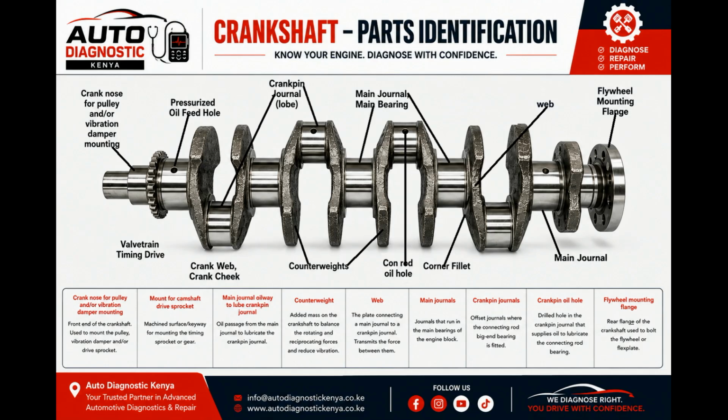Next, let's speak of multi-cylinder crankshaft support. Now, here's something you might not have thought about. Does every crank pin have a main journal on both sides? Not always. For example, a throw crankshaft has only two main journals. The crank pin can be connected by what's called a flying web.